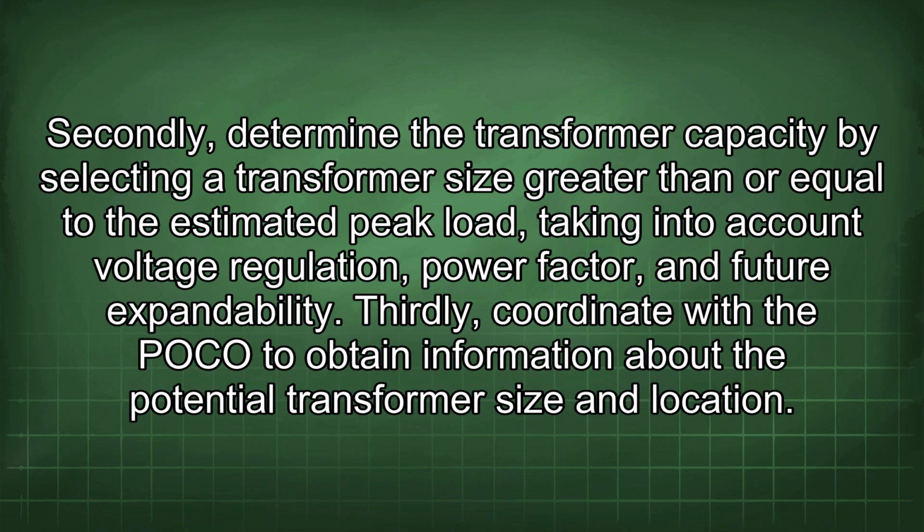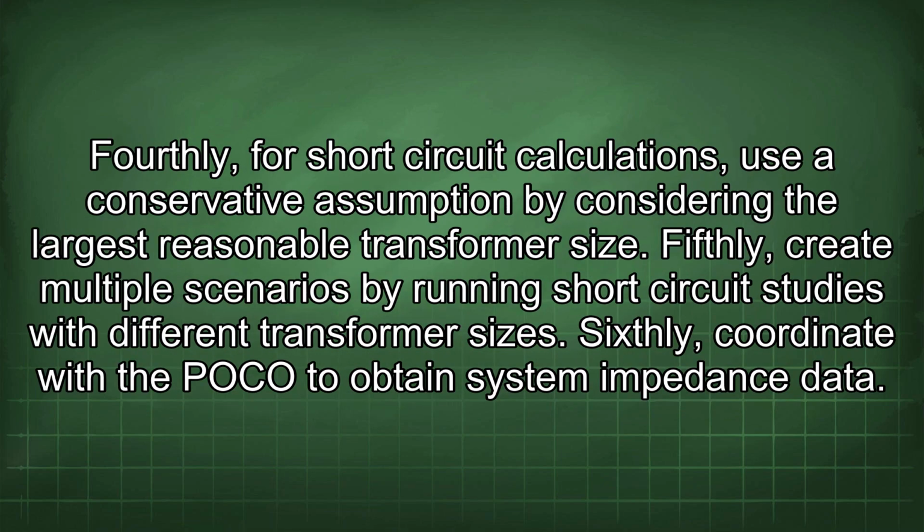Thirdly, coordinate with the POCO to obtain information about the potential transformer size and location. Fourthly, for short-circuit calculations, use a conservative assumption by considering the largest reasonable transformer size. Fifthly, create multiple scenarios by running short-circuit studies with different transformer sizes.